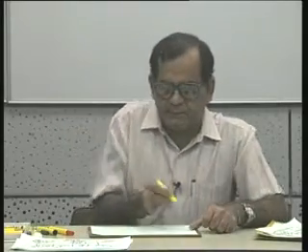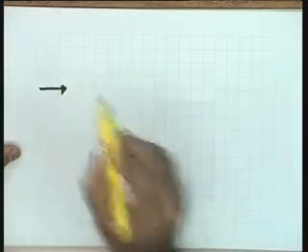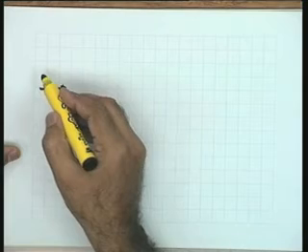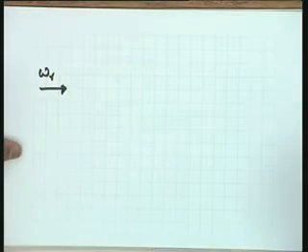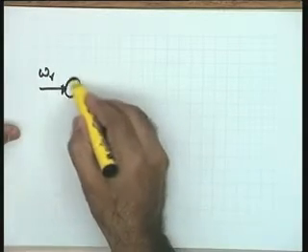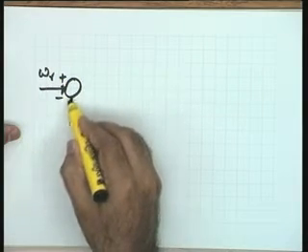So, now let us go back to the original system wherein I have to place the motor and give you the overall transfer function of this overall block diagram of the system. I can take up the unity feedback system. Omega r is the input I am taking. I know that physically it is Er which is being given as the input, but in the block diagram, for the purpose of analysis and design, I could take omega r as the input, plus minus here.